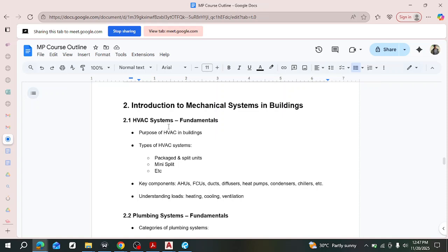Another thing to consider and understand in ventilation is that if you remove entirely all the exhaust air, it's not going to be economic. It's going to be very costly to do that. So there's also an understanding of how to combine the return air. There's what they call return air: the air that left the space can come back, be reconditioned and then sent back into the space. Then, based on what the space is used for, it can also introduce extra air. The quantity of extra air is just like a ratio thing, basically, to ensure that comfort is always the priority.